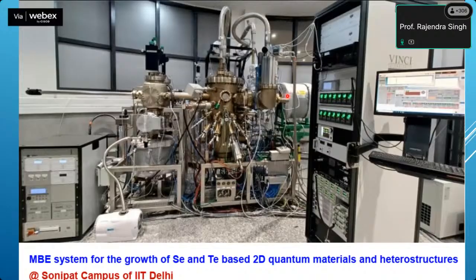Then there are buffer chambers and the storage chamber. When you introduce the indium phosphide substrate or sapphire substrate onto which you want to deposit this semiconductor quantum heterostructure, you have to transfer it from the high vacuum to the ultra high vacuum. This is the chamber where they are deposited, and these are the K cells. MBE is a physical vapor deposition technique.